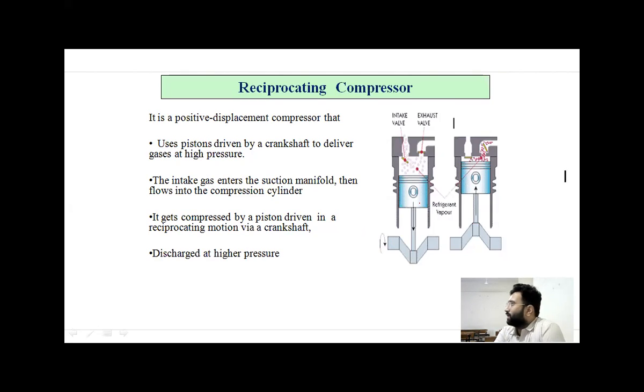So this is a classic piston cylinder assembly in mechanical engineering. What you see at the outside is the cylinder block. What you see here is the cylinder head. So the outside is called the cylinder. Then inside we have the piston, which is a reciprocating part. Then there is a pin, or ring, that connects the piston and the connecting rod. What you see here is the connecting rod, and here we have the crank pin. And what you see here is the crankshaft. Okay, so a classic assembly. There is another subject called theory of machines.